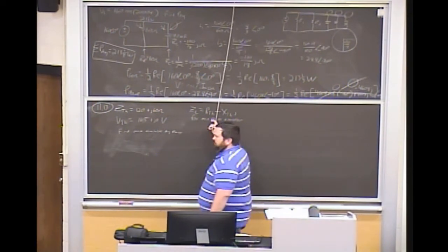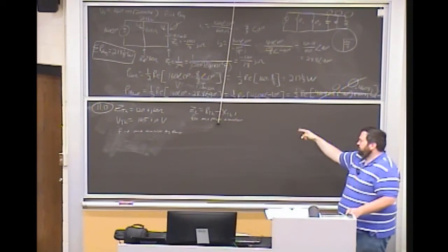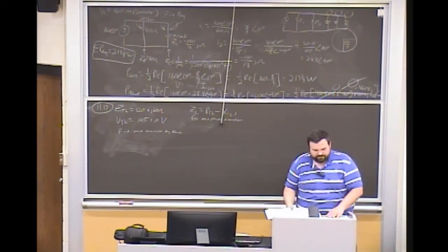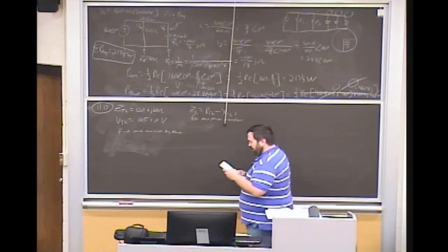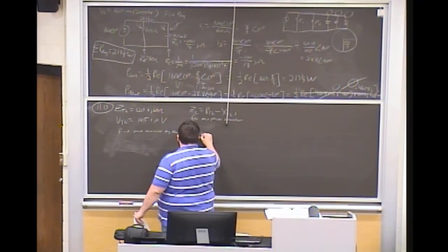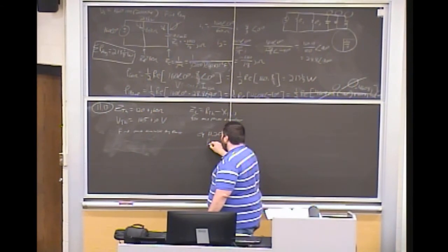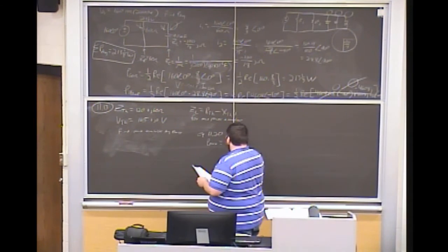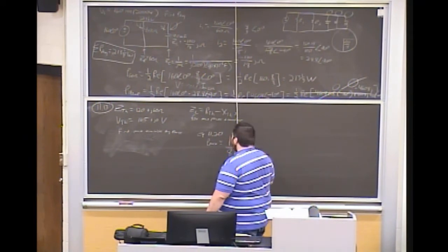What we want for our load, for maximum power transfer, is RTH minus XTH j. Everybody remember that? So it's effectively the complex conjugate of the Thevenin impedance. That's where we get our ZL for max power transfer. And what we did was plug this in and figure out the maximum power. It's derived in your book, from equation 11.20, the maximum average power you can get is equal to the magnitude of VTH squared divided by 8 times RTH.